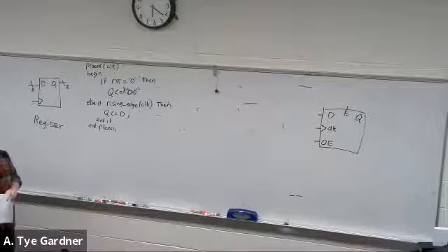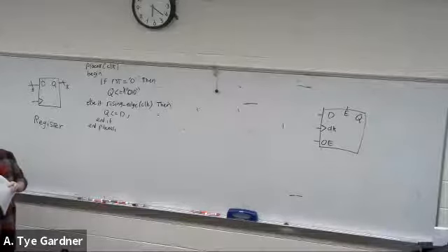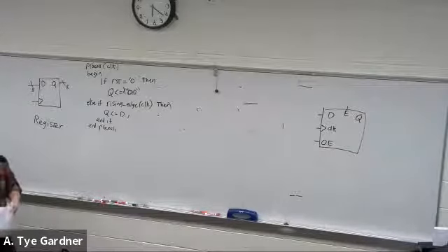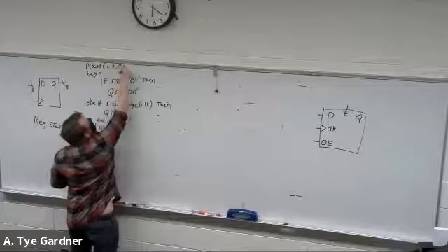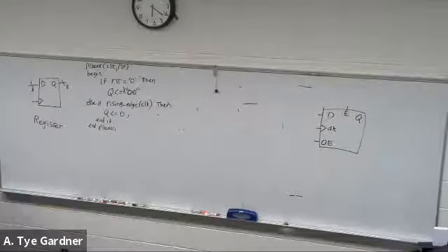No idea? It's okay. We could add a reset to the sensitivity list. Exactly. Now that will execute if either clock or reset occurs. And then the first thing that gets evaluated is reset 0. So if reset changes and it was 1 and now it's 0, it won't evaluate Q in any other way other than to set it to 0.